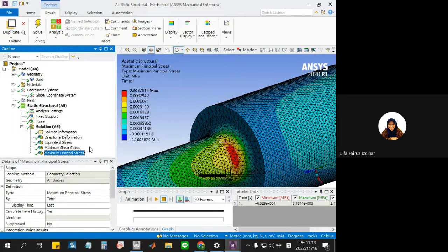If you are conservative, you need to use shear stress to estimate your safety, because your safety is lower. If one day in the future in a company, your supervisor asks you to design something and you need to know your safety, then you need to question yourself or your colleague: do you want to be more conservative or less conservative?